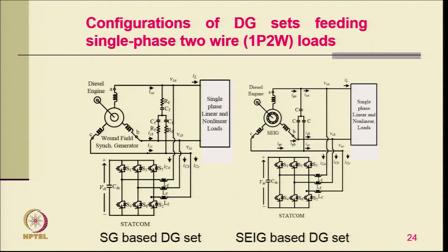This is the typical case when you have a single phase load on a 3 phase synchronous generator. Then you will have load unbalance, and the voltages are distorted if it is a non-linear load, and voltage unbalance is also present there.